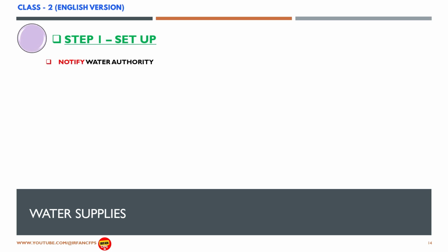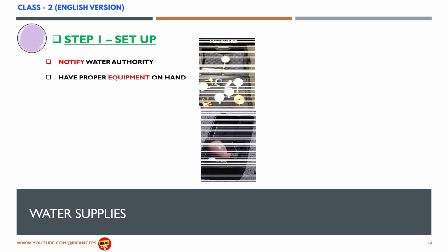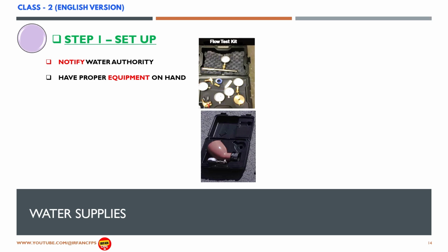Let's discuss the flow test procedure in great detail. Step 1. Setup. Notify water authority that you are going to perform the flow test. Have proper equipment, flow test kit on hand.